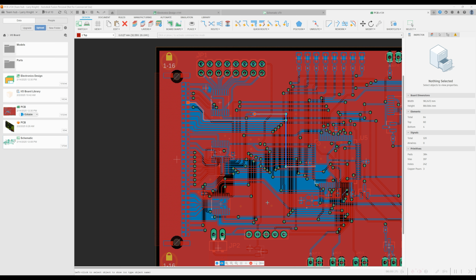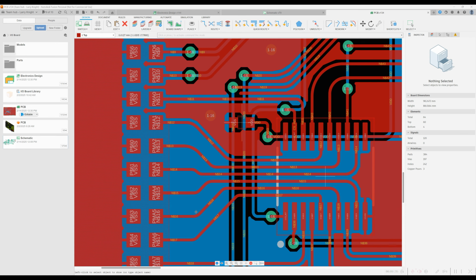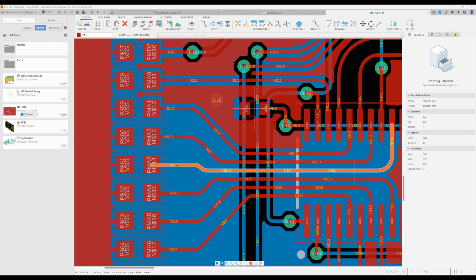And then with a 100K or a 10K resistor tied to VDD, if we touch it to the address lines here, it should pull them high. Because if the SRAM chip is turned off in its high impedance state, then even a 100K resistor should pull these high. If it doesn't, then the SRAM is forcing a low state, since they were all low.